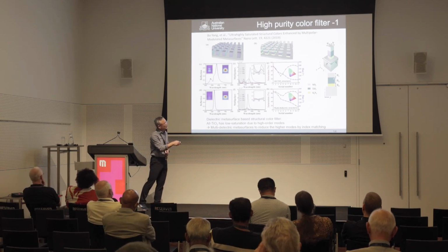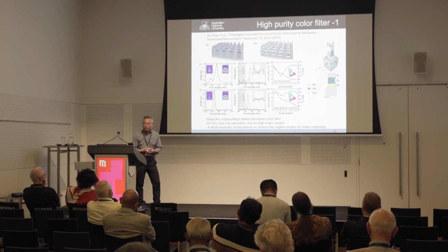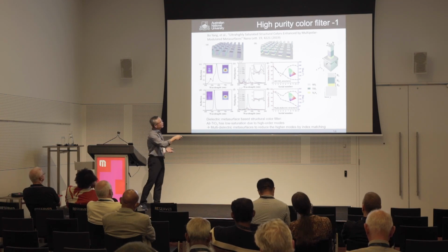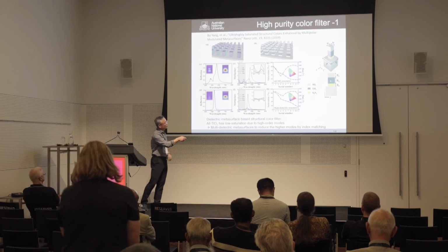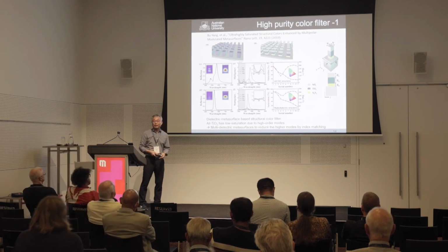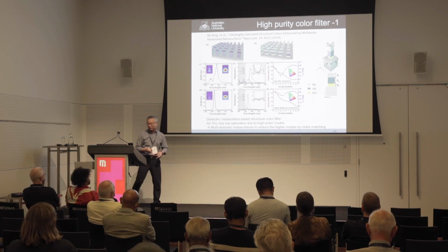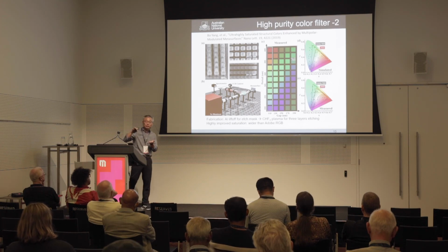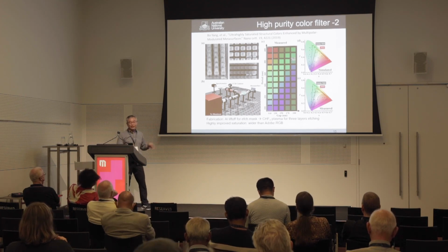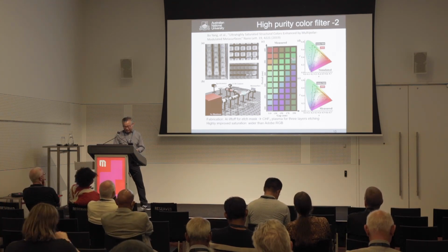Titanium dioxide is sandwiched by silicon dioxide and silicon nitride on top of silicon dioxide. So it's a sandwich structure. The refractive index gradually changes from 1, 1.5, 2.5, 2, and 1.5, so that only one single mode exists. In the fabrication, on the glass, 3 layers are stacked together, and patterned and etched all at once using CHF3 plasma. So it's not a big deal.